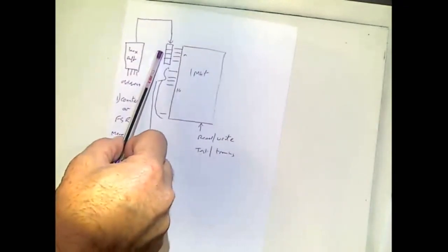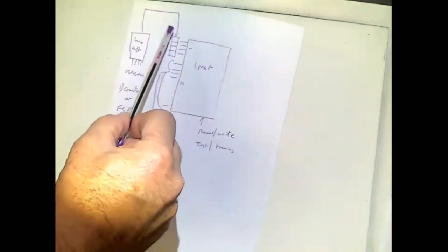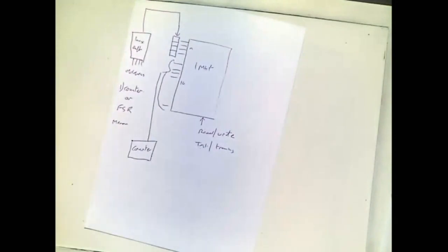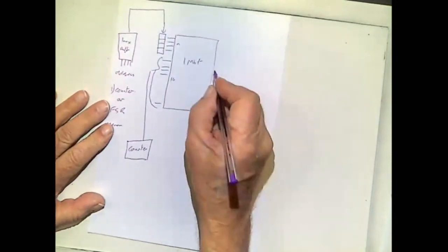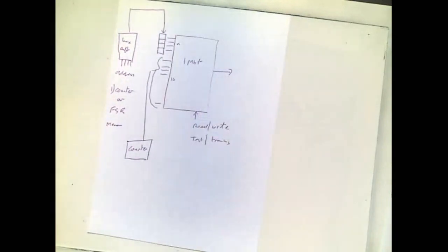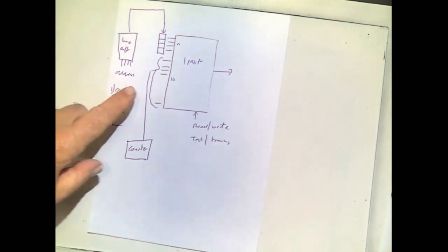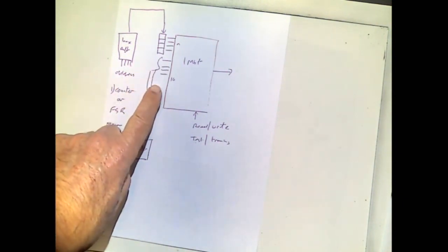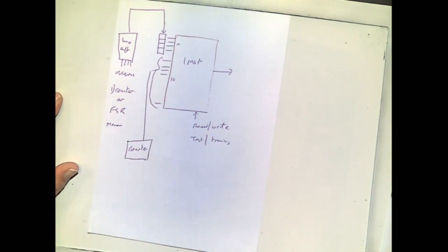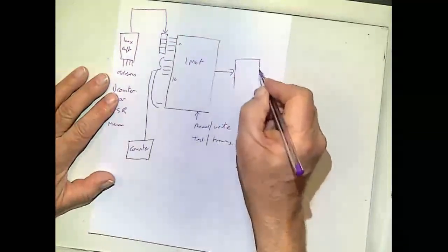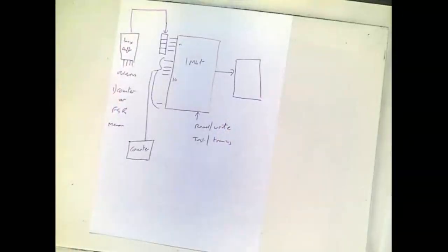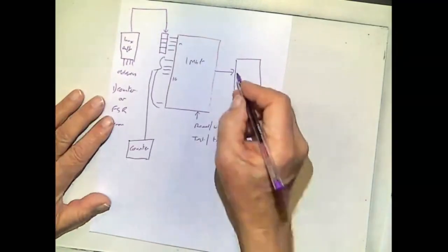We are taking the interval from the new data, and we are accessing the information at that location, and that comes out. The output is a single line because we're outputting the bits. It's a random access memory, and I want to sum the activity over all 2 to the 16 functions. I've got a single output, it's producing a stream of ones and noughts. I want to know the totality of ones and noughts in it. What do I put on the output there? Another counter, counting up the noughts and ones. And so this would be an asynchronous counter.